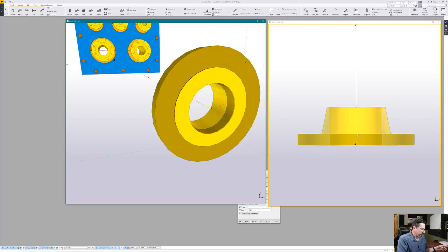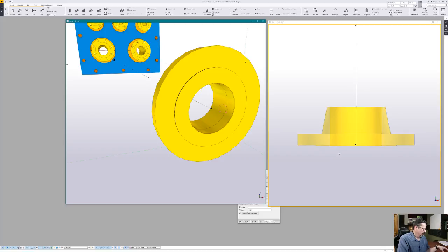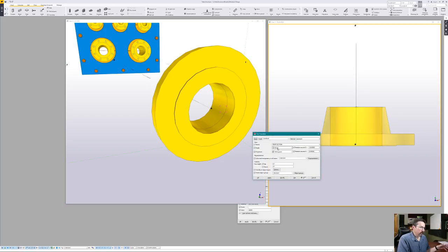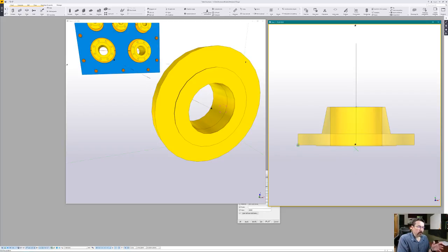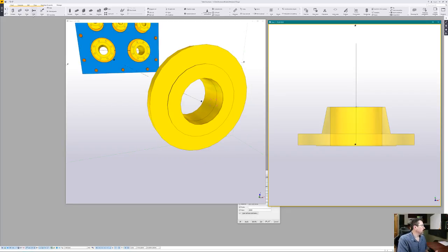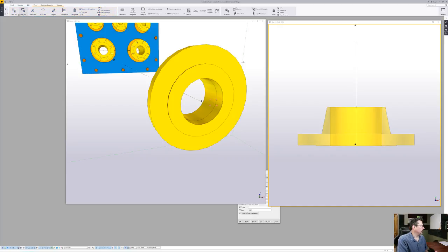In order to do that, I'm going to create a temporary section. I have one already set up as standard, also called temporary section, that I can load up and apply. Then I'm going to create a new view using 2 points. I have macros set up on my keyboard because I use these all the time, but basically, if you go into view, you start a new view, you pull that down, and in here there's one called using 2 points.